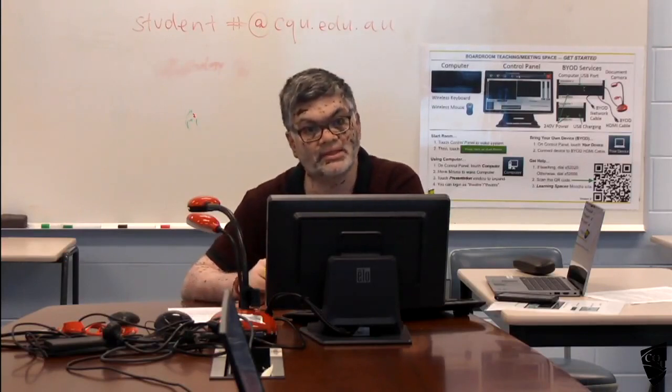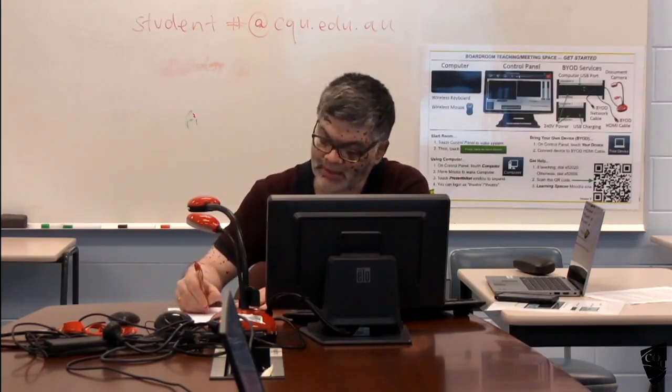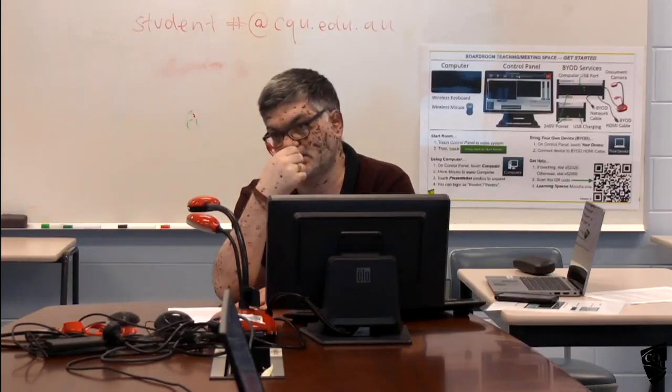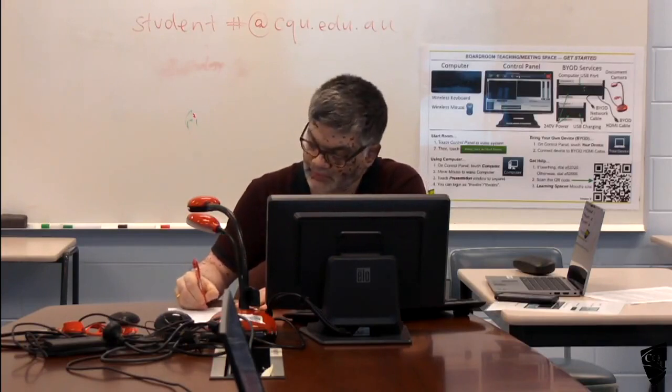If it is a discontinuous edge, then this mid-span moment should be multiplied by 0.5. If it is a continuous edge, it should be multiplied by 1.33.